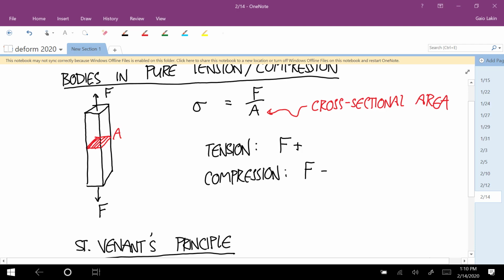And Saint-Venant's principle, which is just an experimental finding, is that yeah, the stresses in here are going to be basically exactly the same for the point load as they would for the uniform distributed load. The only places where they're going to be different is close to the ends. So if we're going to use other ways to calculate the loads at the ends, we can sort of gloss over the fact that the way the loads are applied might be different in two different cases.